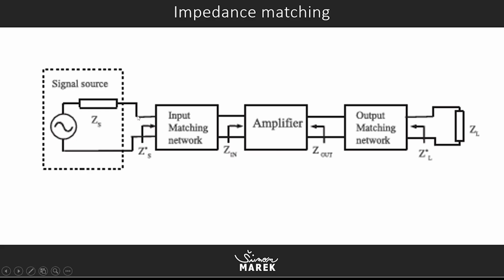All you need is an impedance matched trace. So your trace is really 50 ohms impedance, and just plug your signal source or some instrument, either VNA or spectrum analyzer, and this is all you need to do for your LNA amplifier matching.